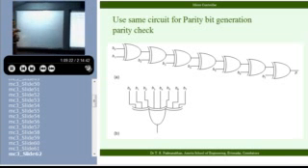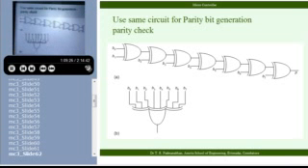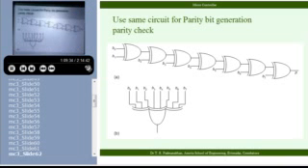Both are 0 or both are 1, I get a 0 here. If they are unlike, I get a 1 here. So by putting exclusive gates continuously, I am implementing an odd parity check. Okay? By repeated use of exclusive gate, I do an odd parity check. For an even parity check, I have to just put one more gate, that's all.